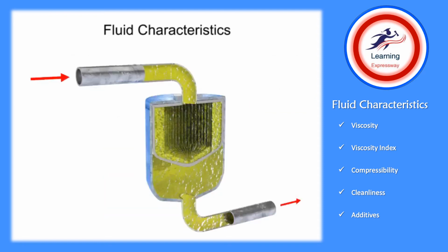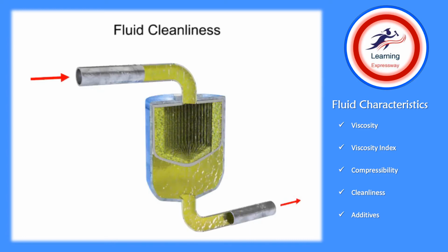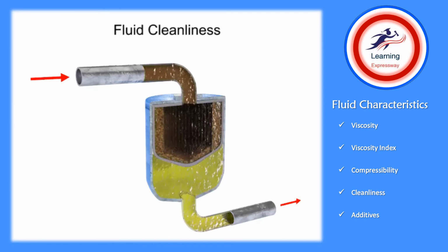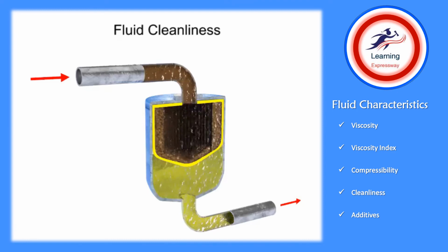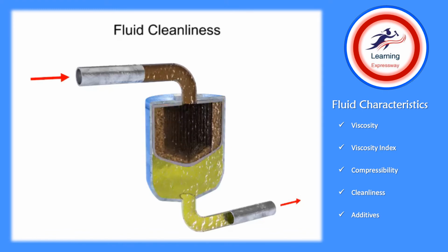Several factors should be considered when designing a fluid system that uses a petroleum-based hydraulic fluid. The first is cleanliness. Oil never wears out, but it can become so contaminated that it is unfit for further use. Fluid systems frequently employ filters throughout the system to help reduce contaminants. They may also require complete fluid replacement after certain time intervals, and this can become cost-prohibitive with larger systems.